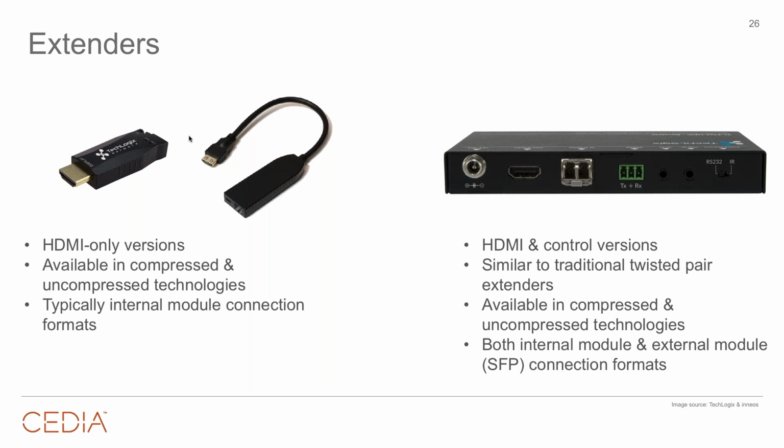these extenders look a lot like an HDBaseT extender, right? They have HDMI ports, they have control ports, depending on the model, Ethernet, ARC ports. The only difference is instead of that RJ45, you see a fiber connector.